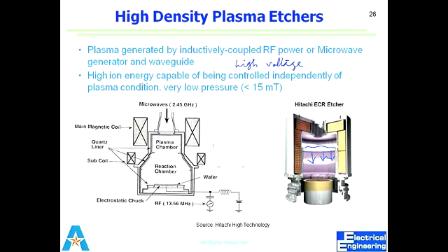Okay. Now when I again go for the next cycle, that is the etching cycle, it will etch sideways as well as downways. So this part, due to the isotropy, would be etched this way. But so far as this part is concerned, laterally only that passivation layer is etched. So that passivation layer has avoided the etch. So this way it continues. You can see that instead of having something like this, I have achieved something like this.